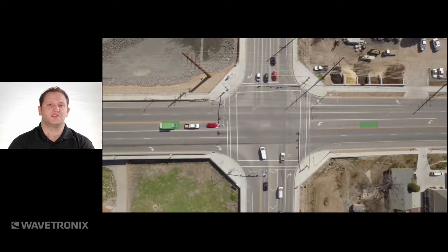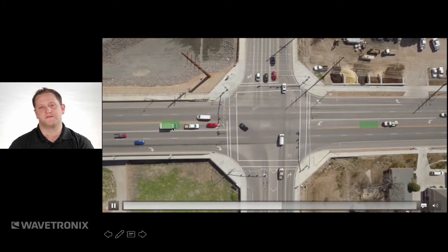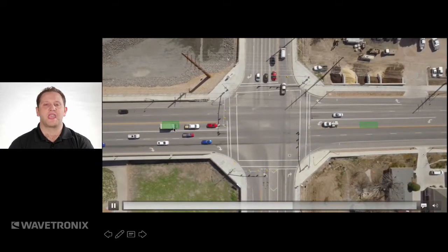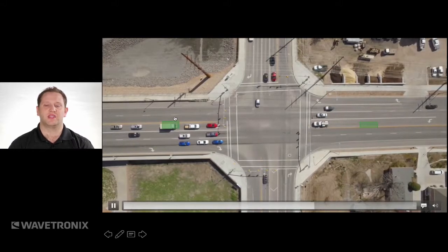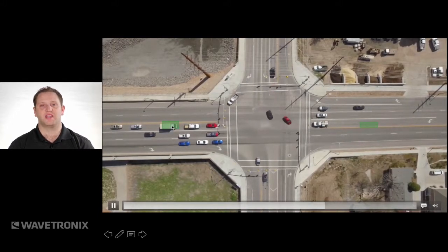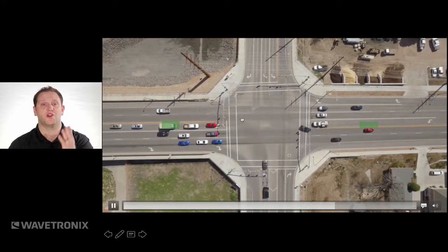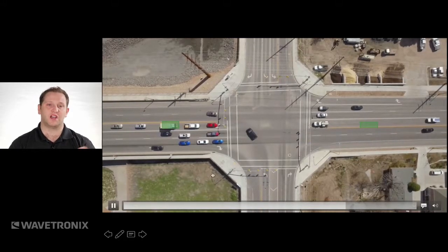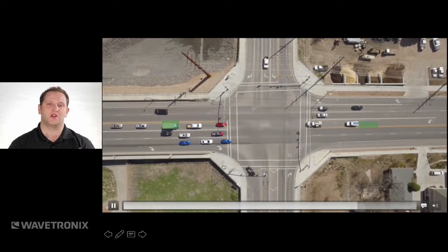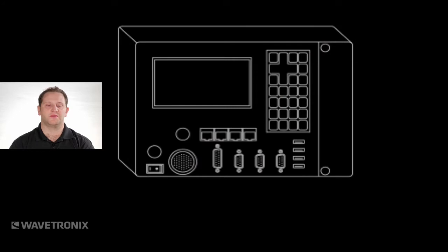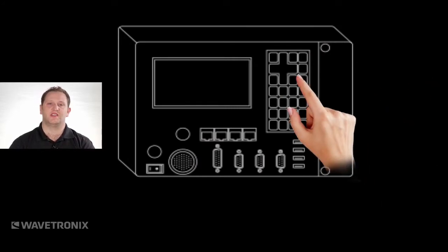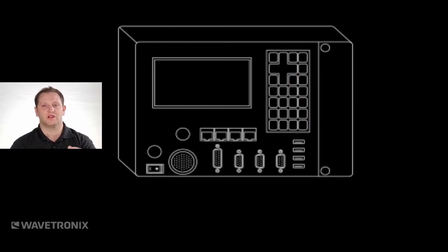So you put that zone about 50 to 65 feet away, and then you put a 3-second or so delay on it as well, so that if that is occupied, as you'll see with these vehicles, they'll get a green arrow, and then they can go. If it's not occupied, then it won't get a green arrow, and those two cars will be able to sneak through on yellow. So in the controller, you have to make those changes. You have to go in and change it to be lower, add a delay of about 3 seconds.